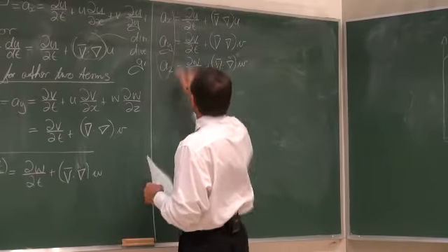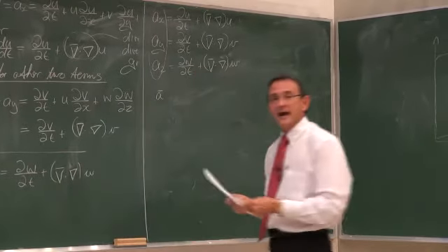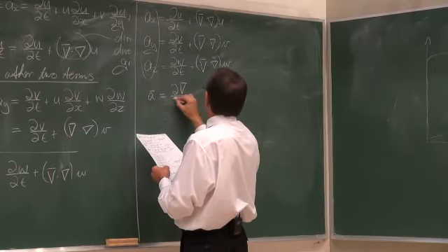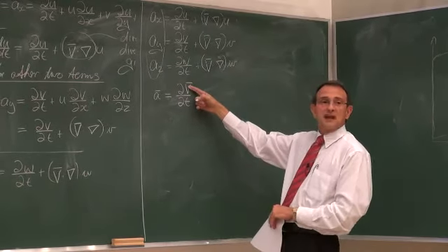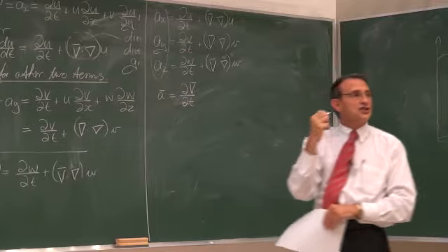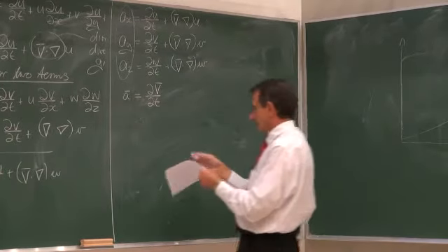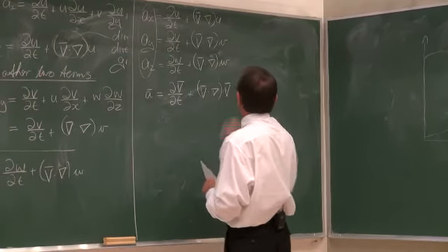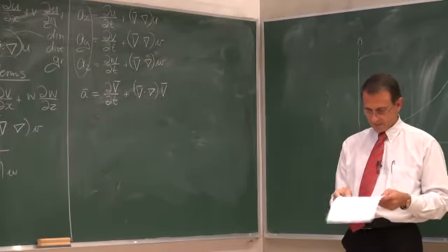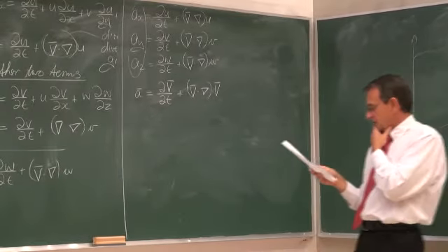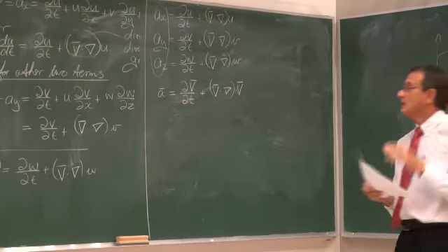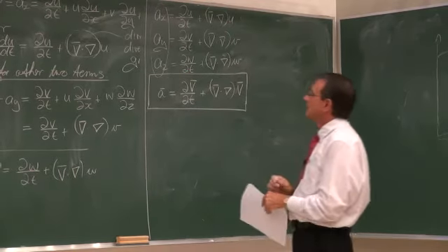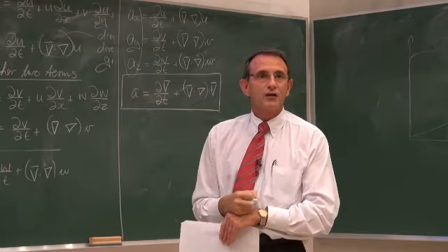These three terms are the acceleration vector a, equal to partial dV dt, the velocity vector V with its three components u, v, and w, plus the velocity dotted with the gradient of the velocity vector V. That in general is the acceleration, written in a very compact form.